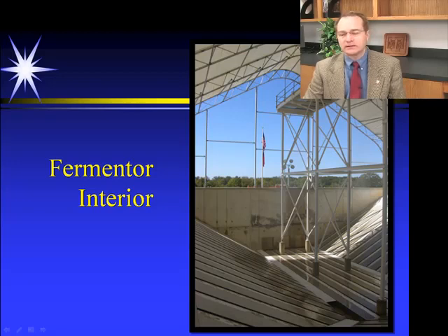Next, what you see is us loading 300 tons of biomass into the fermenter. The biomass comes with a front-end loader, and then there's a kind of fire hose with a mixture of water and lime, and the idea is that water, lime, and biomass are all blended together, and they then sit there for about a month roughly. We blow air up through the pile, through those gratings that you saw on the previous slide, and the combination of air, lime, and water takes out lignin, which is the glue that holds the biomass together, and hence makes the biomass very digestible.